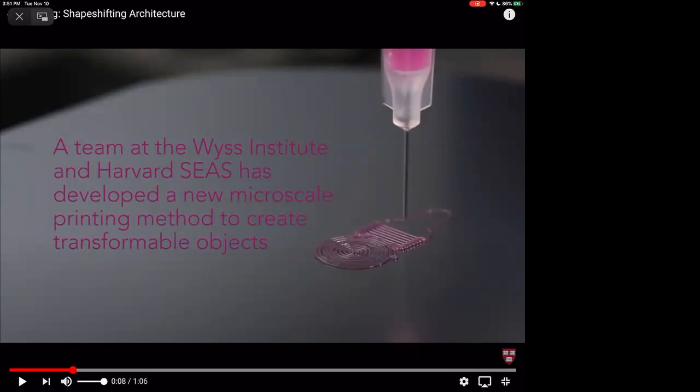But you'll notice that the tool path, or specifically where they lay down the different filaments, really matters in this structure. What's interesting about this paper is it's all the same material. It's not two different materials, it's only one material, but the orientation of the material is different depending on what structure they're interested in. It's not just to make it look pretty, but the deformation of this material to get the structural change that you want really depends on orientation. That's why you have different tool paths in different parts of this component that they're building.